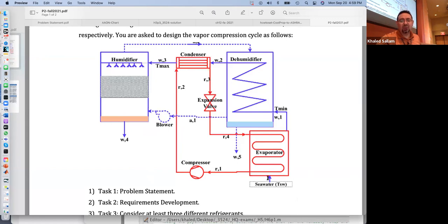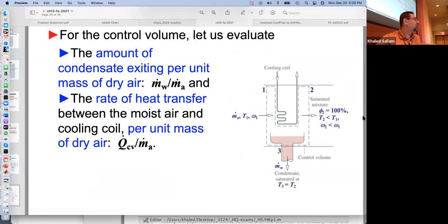So why does he need to cool? What is he cooling? He's cooling water. He's cooling very cold water. Okay, why? Because that water over here goes to this chamber, called the condensation chamber, where hot, humid air is coming. And this hot, humid air, when it sees that cooling coil, what happens to it? He comes in humid and hot, and he leaves cold and saturated.